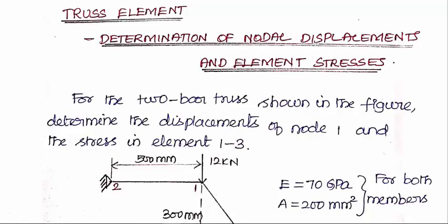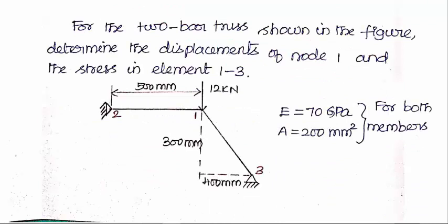How to determine the nodal displacements and element stresses of a truss element using the finite element analysis approach. Let us discuss this in this lecture video with a problem. For the 2-bar truss element shown in the figure, determine the displacements of node 1 and the stress in element 1, 3. The truss element given in the problem is constituted by two elements.